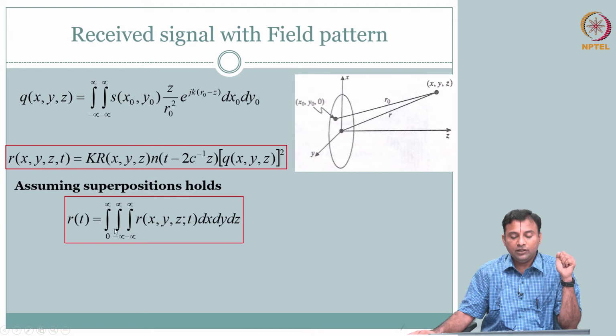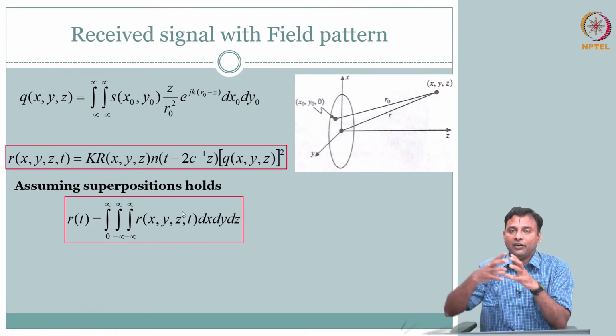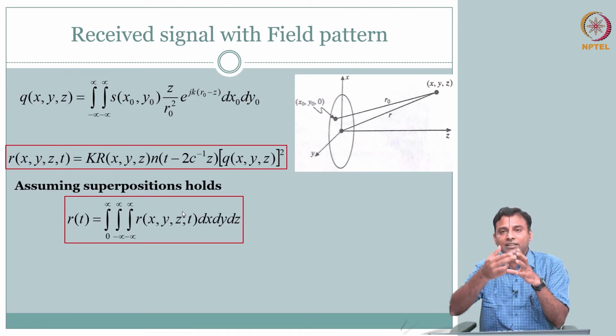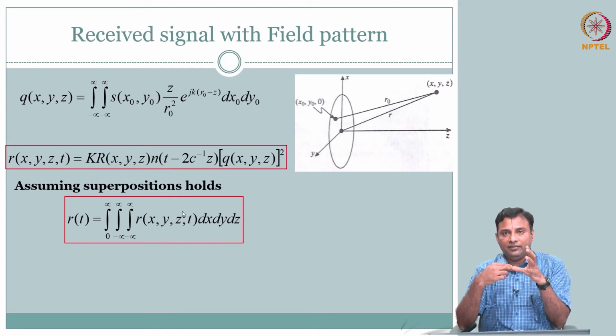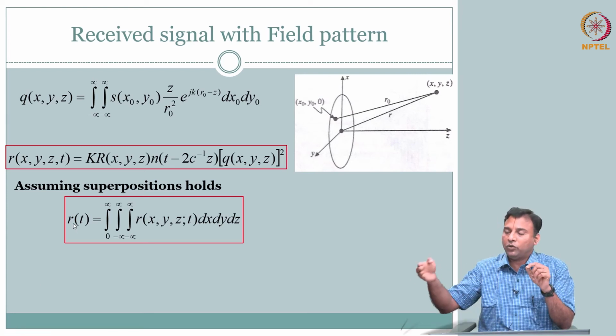It is capturing all of this from the whole region in front of the transducer where all this pressure went. Everything on the surface of the crystal is going to be summed. So you are going to have an R that is a function of t, because the wave is travelling and the echo is coming.